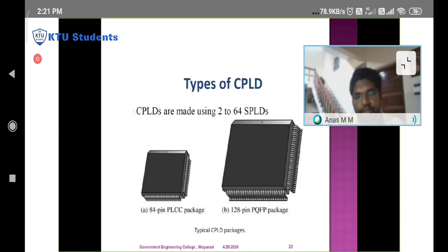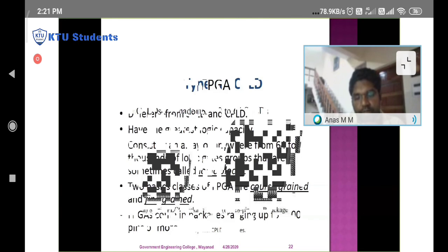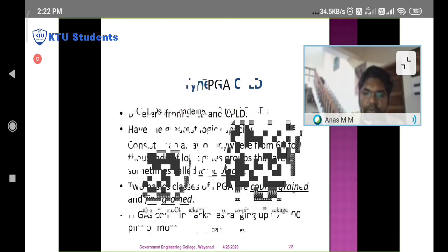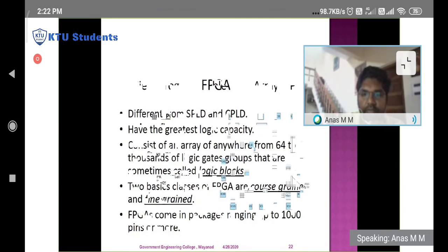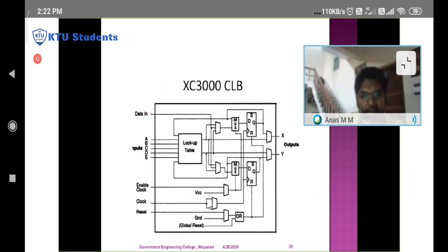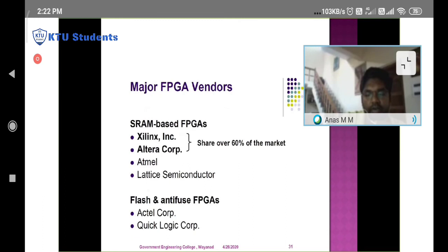These are the ICs available in industry with different sets of packages. For example, if you want to implement a 4-bit processor, you don't need to use an FPGA. You can use a CPLD; CPLD hardware is enough to design a 4-bit processor. But when it comes to a 16-bit or 32-bit processor, you need a bigger system, a bigger FPGA, and different types of families like those shown here. Xilinx or Ultra families have Virtex or higher versions of FPGA families with billions of transistors. So transistor count and logic blocks are the important factors, and they decide how big a system we can implement in FPGA.